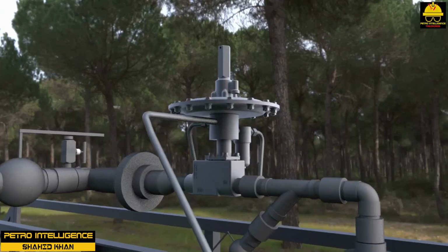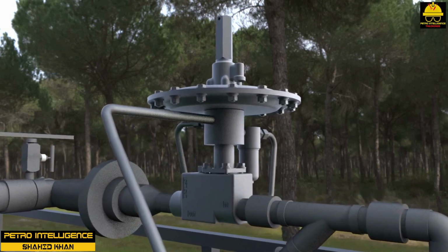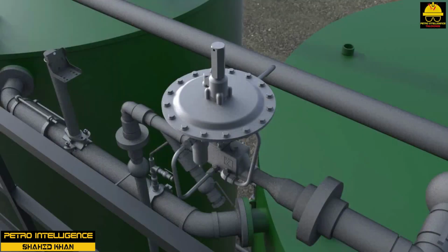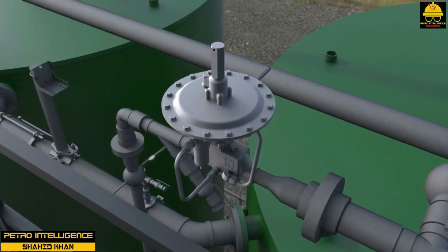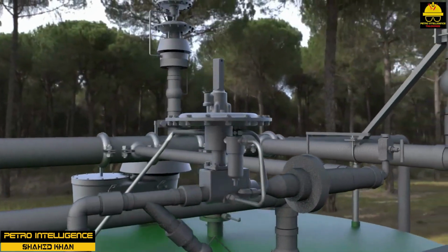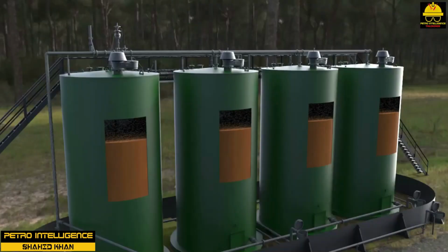Gas blanketed tanks. Depending on the vapor pressure and temperature of the stock in an atmospheric tank, the vapor space may be filled with varying mixtures of vapor and air. The vapor space in tanks storing materials having a low vapor pressure at the storage temperature is usually too lean to explode. The vapor space in tanks storing very volatile materials is usually too rich to explode. In some tanks, however, the vapor space would be nearly always in the explosive range if air were allowed to enter. Gas-blanketed tanks are used to store these hazardous feedstocks.